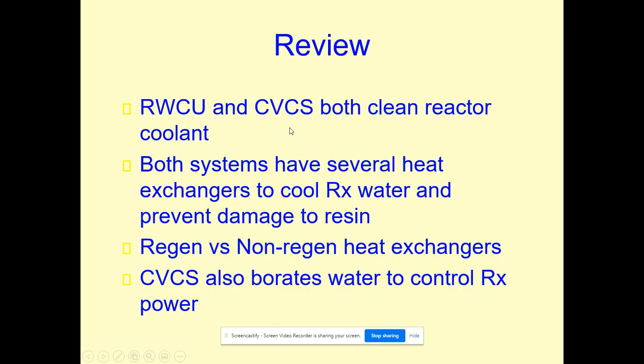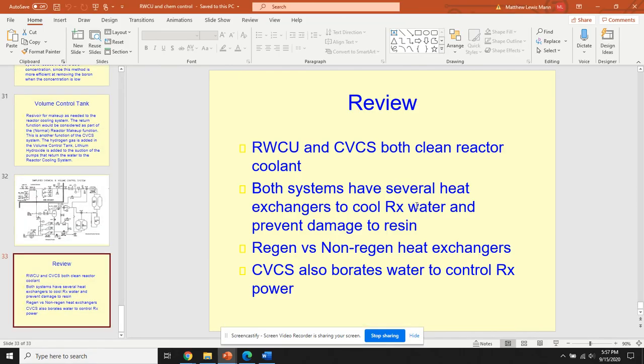So reactor water cleanup and CVCS both clean the reactor coolant. They both have several heat exchangers. So there's only two on that particular drawing, but that's just for show. There are going to be more heat exchangers even in a pressurized water reactor. And you need to know the difference between the regenerative and non-regenerative heat exchangers. And CVCS has some extra job. It's going to borate the water, and the purpose for that is to control reactor power.